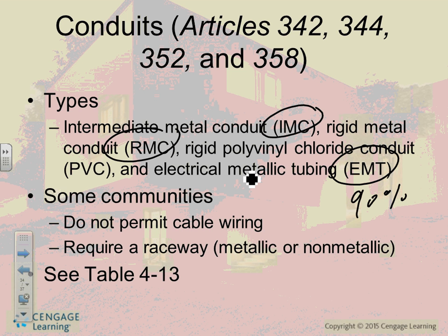Okay, what's the intermediate though? The intermediate, guys, this is how thick that is compared to this. I don't know if you guys can see that. There is one in between them, a size in between. So from the point of view of the code, the intermediate and rigid are treated the same, for severe physical protection. So that's what you do.